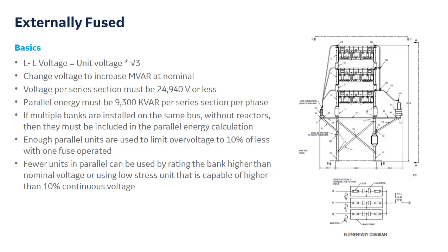Over here, we had the line connection come into the arresters, and from each arrester in series, we came up to each phase. The downside of going to a 2-series capacitor bank here is each rack does need to be insulated, where before each rack was tied in together.